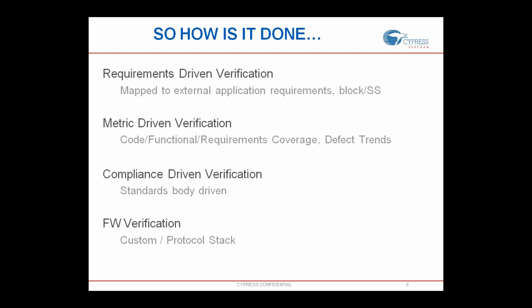Because firmware also talks to the hardware through registers, hardware also talks to firmware through registers, but there are assumptions made. There are timing assumptions made by firmware, there are timing assumptions made by hardware. So therefore, the firmware verification is extremely important. It may or may not be possible to run a full chip's RTL simulation with the entire stack running. You may have to plan for validation, or you may have to plan for emulation.